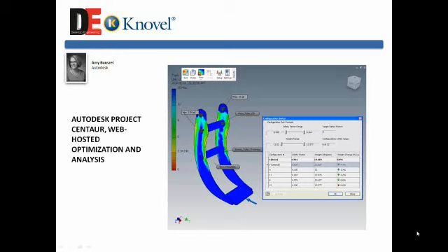So again, sometimes it's not the fastest method if all you're interested in is just creating 3D geometries, because you do have these equations. Sometimes you might have constraints. So if you're trying to modify some of these geometries and it's overly constrained, you might find that you actually can't make that modification. The CAD system won't let you do that if you're doing something that it thinks is wrong. So again, rapidly repurposing or making dramatic or radical changes to this type of design can be a challenge.